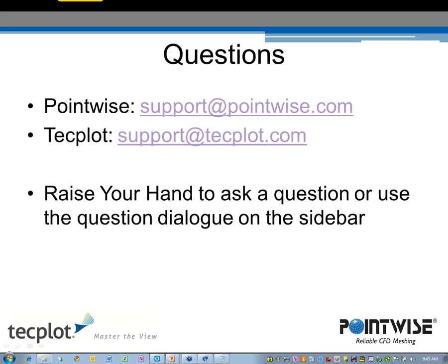Hi. Actually, I typed in a question before. I was referring to a plot where you had the coefficient of performance plotted against the tip speed ratio. You correctly said that the trends of the CP look the same, that there's an optimum at a particular tip speed ratio, which tends to fall on either side. But what I thought was that at tip speed ratios of 1, these Darrieus wind turbines give very low coefficient of performance.